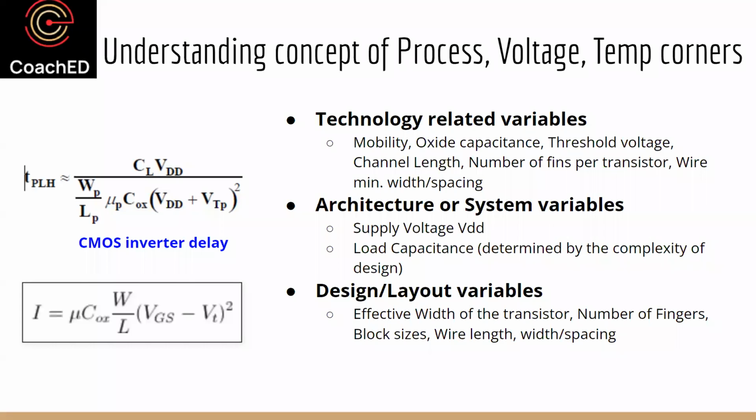In the same way, when you're doing chip designing, it is something which you have to account for, and something which you have to consider when you are designing the chip. Why? Because you may think that, okay, my chip meets the spec. I'm going to assume some channel length value, some width value, some threshold voltage value, and even some supply value. And I'm going to assume some propagation delay or some current. But in reality, it never happens like that. It is actually a distribution.